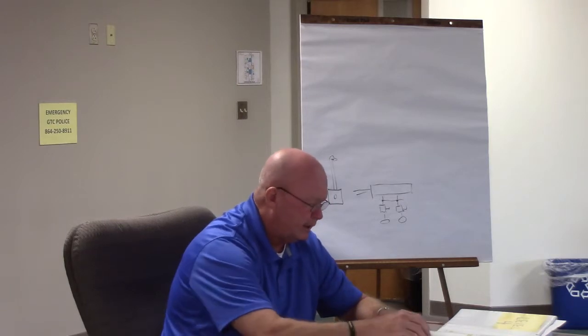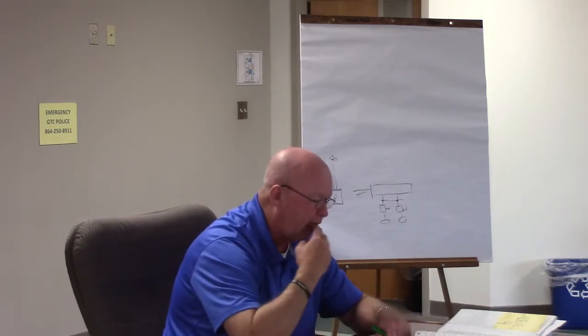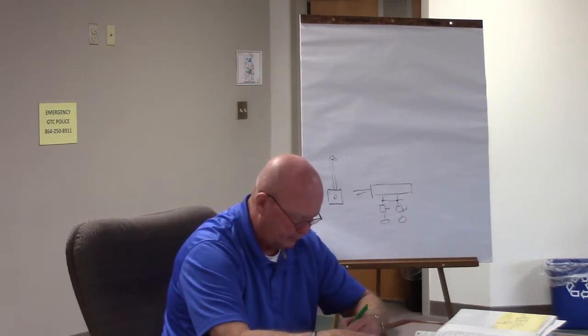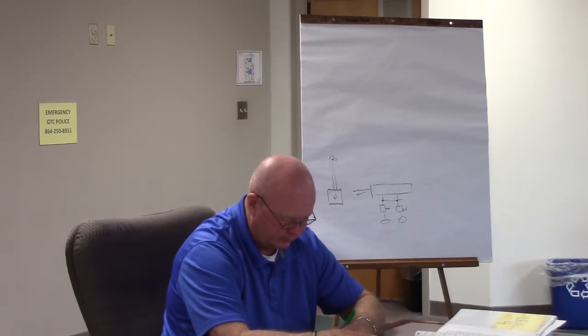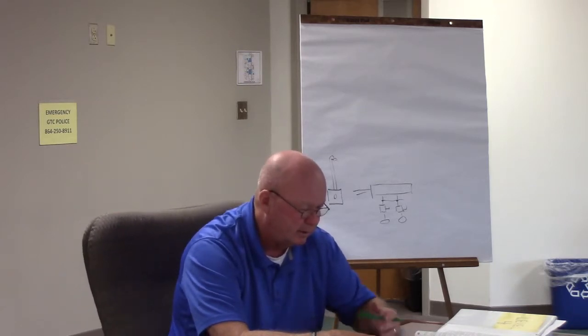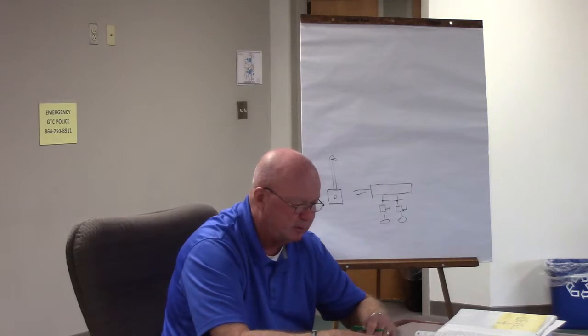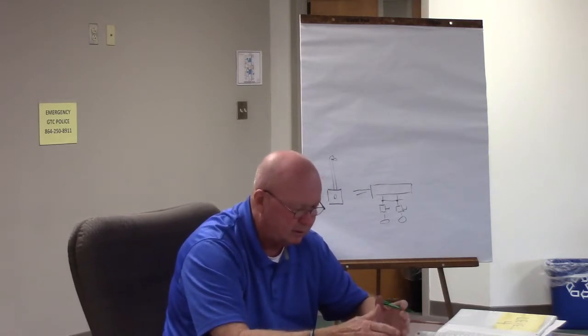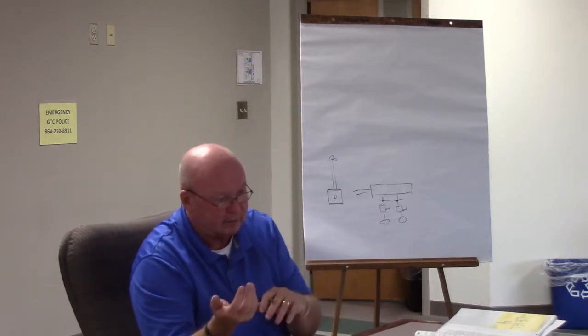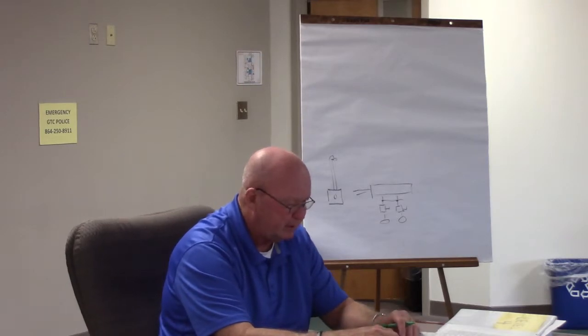Okay. All right, number 15. Demand factors for neutral conductors can be found in NEC section 220.61. Okay, C2. Yep. 220.61, that's the primary place. So 220.61 is good enough. If you go to 220.61, C2 is found inside of 61. So 220.61 is good enough. And that's found on page 11.